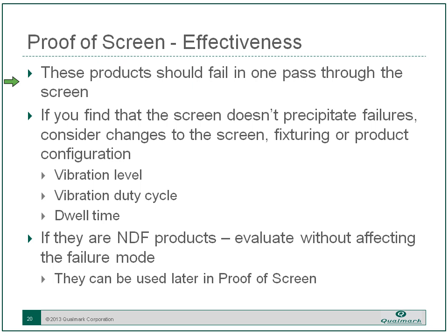One of the problems, and places where you have to do some intelligent decision making that will come up, is that in HALT we'll often do the testing with the cover off the product and maybe other modifications for airflow, etc. But in HASS, you're testing a full up product, so you have a different product configuration. Maybe you think about doing HASS before you put the top cover on, and put the top cover on at the last. So those are things to consider.